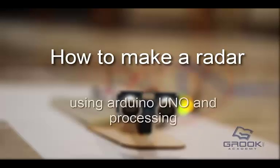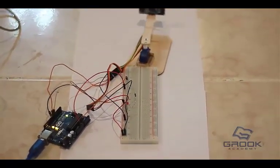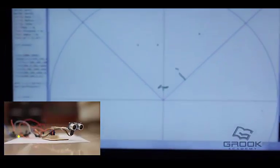How to make an ultrasonic radar using Arduino Uno and processing application. Now, the radar is rotating 90 degrees and calculating the distance away from the ultrasonic sensor. It is sending the data, angle, and distance to the computer using serial port. The processing application is converting the polar to rectangular coordinates and showing them on screen.